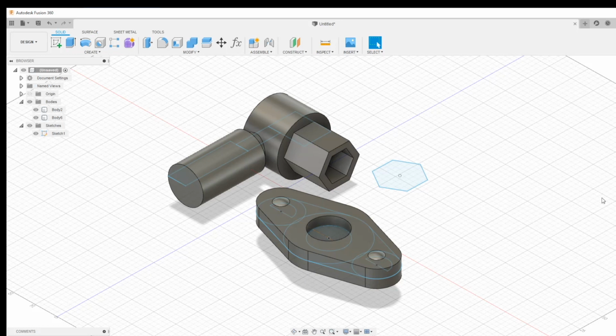I'm going to use my just set parameters along with the feature-based philosophy of Fusion 360. You might remember that at the beginning I talked about the feature history controls. Can you see this section is now populated with icons? This represents every operation I've made in my work area, and with the player controls I can move through them and change any moment of my history.